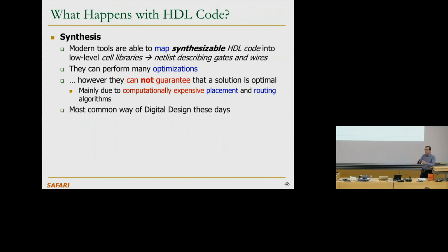You write Verilog code and you give it to some software algorithms and they generate the netlist, and then that netlist somehow gets transformed to real hardware. But this is basically the specification of the hardware. And most companies use these tools to improve productivity. But there are some parts, as I said, that are really performance critical, that no synthesis tool generates efficient or fast circuits for. As a result, you need to do it by hand. Hopefully that's not a large fraction of your design.